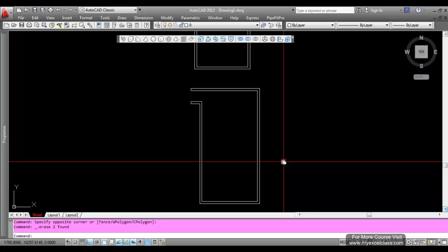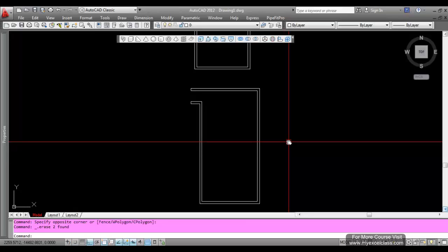So you can select how you are going to start your project. You are going to go center line based, or justify left based, or justify right based. Some companies and some works will be prepared based on outer to outer. Some projects will be based on inner to inner. Some projects will be based on center to center. In industrial work, normally they will use center to center, so that they will give the grid and all other things. Now you understood very well.